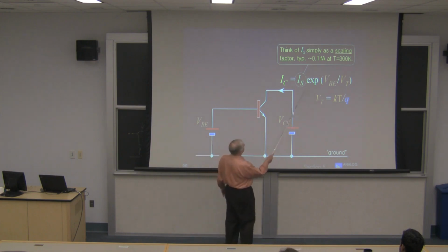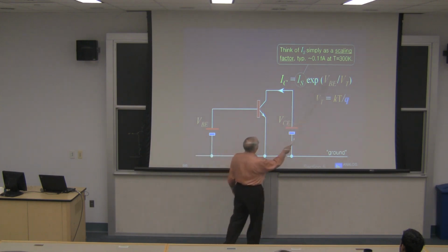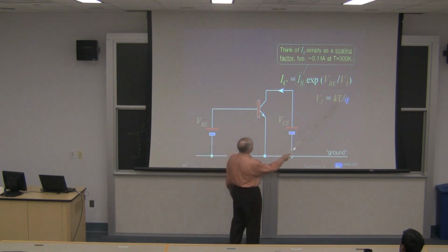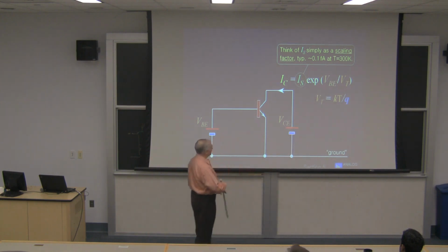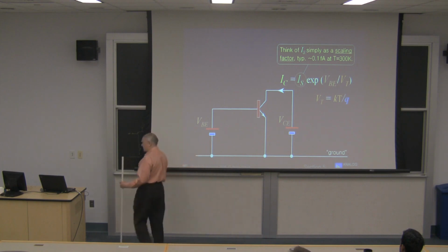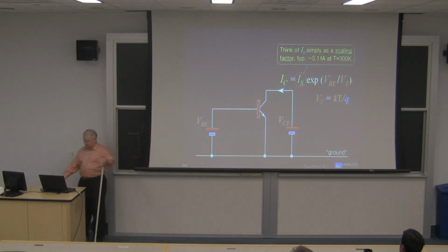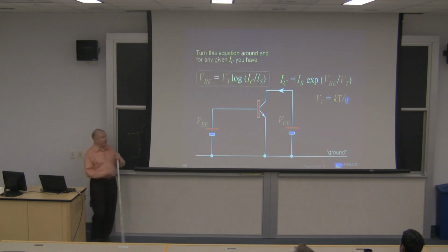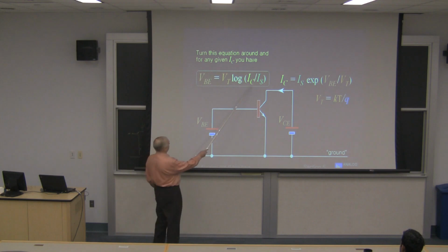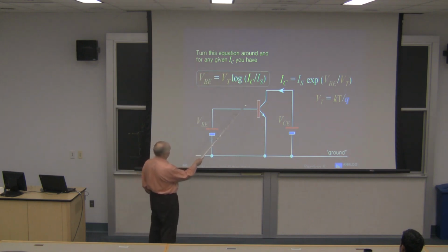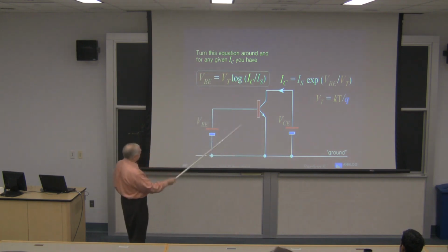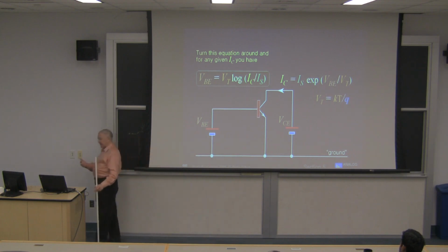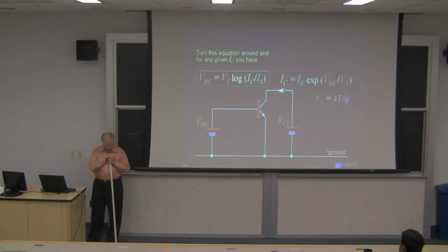But then, because it's an exponential property, we cannot take the exponential of the voltage. It has to be scaled, and marvelously is scaled by kT/q, and that's really the whole story. You'd be surprised how close to reality that is. Maybe you wouldn't, but it still surprises me. Now we can turn this around and say that for a given collector current, the VBE is going to be thus and so. It's the same thing, just put another way, but these are very dependable ideas. Now I have to add one little caution.